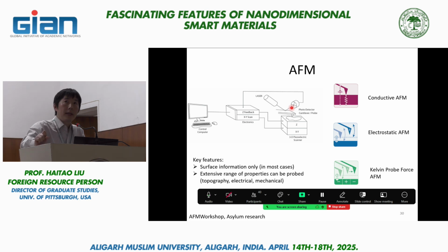In the middle is so-called electrostatic AFM. This is a more complicated case. Here you do two different kinds of measurements. First, you do a topography measurement, so you get a sense of what kind of surface topology it is. And once you do that measurement, then you come back and image the surface again, but do it slightly differently. You're going to lift your tip a little bit up, about 10 to 100 nanometers, typically several tens of nanometers up.